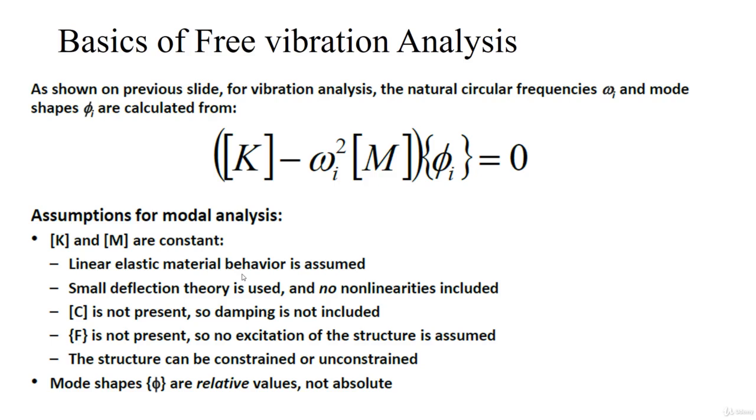In free vibration analysis, we are not going to consider the damping effect, and as I told you, we should have a force matrix which is also not present, because in free vibration analysis there is no external excitation of the structure. And the structure can be constrained and the structure can be unconstrained.